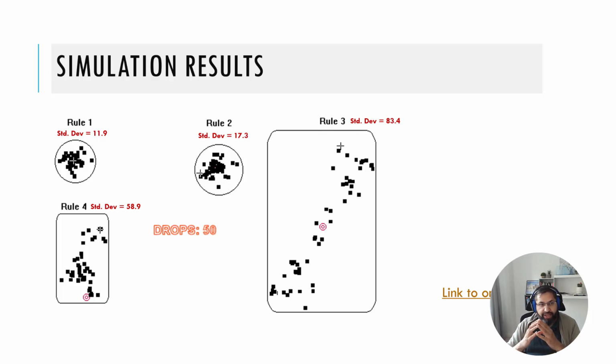So when you have variation that's inherent to the system, messing with the system by tuning, by reset and tune, by calibrating is not going to help. Anything you do to the system is only going to increase the variation, because you have variation inherent in the system that you can do nothing about, and your actions add more variability. Which is why rules 2, 3, and 4, all those other strategies where you do something to the system, end up in increased variability.